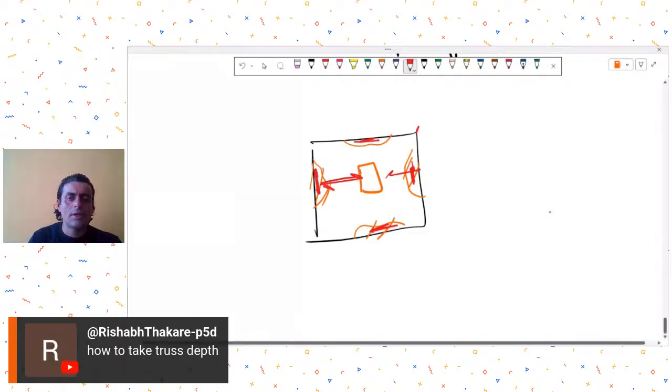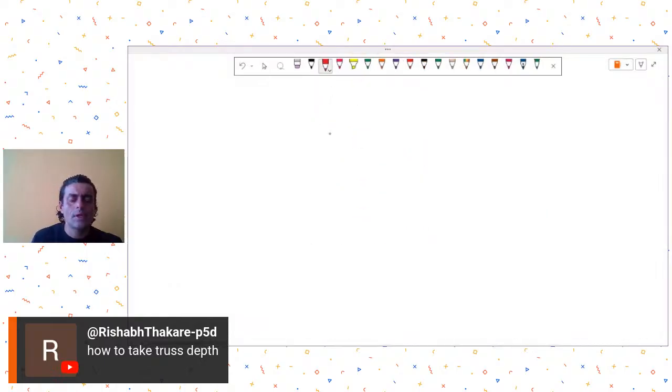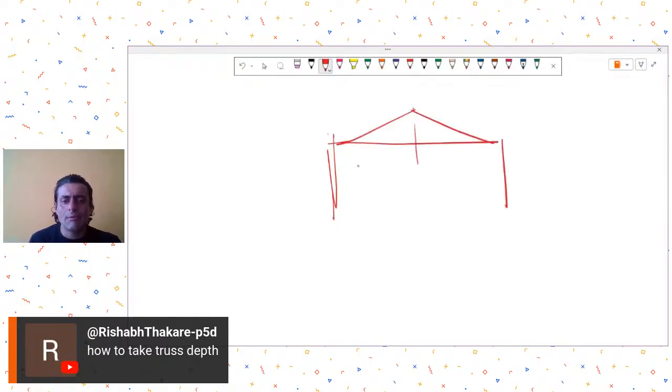No, it depends on, first of all, you need to decide your slope. If you are having a truss, then you need to decide the slope. What is the slope generally you want to provide? Most usually for trusses, we may go for 1/5 to 1/6 of the span. I mean, the slope, we try to go for 1/5 to 1/6. That means, let's say if it is 15 meters, half of it is 7.5 meters.